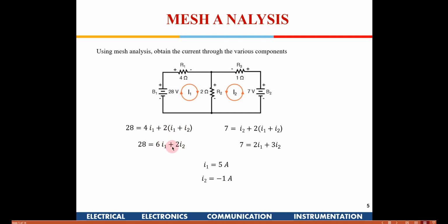This is the first equation, which consists of 2 variables I1 and I2, which we got from the first mesh. Is this aspect clear to all of you? Is this much okay with all of you? Yes, sir. Okay. The silly mistakes which students generally make in the exams are that they mess up the polarity. If you put one negative sign wrongly, whereas we are considering the current like this, then your whole answer goes for a toss. So just in the first framing of the equation you tend to make mistakes, so be careful with the signs which you put there.